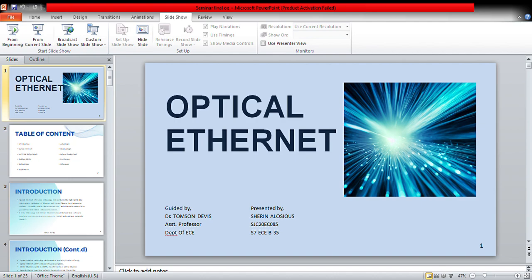And next, what are the key optical Ethernet technologies? That means PAM for modulation. This modulation, pulse amplitude modulation, is a technique that encodes multiple bits of data into each symbol. It is used in optical Ethernet to increase the data rates of communication. This modulation is used, and there have been signal speeds up to 400 gigabit Ethernet.